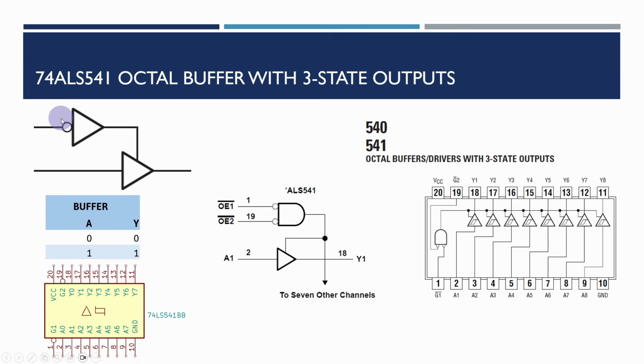And so when the outputs are disabled, generally with the circle here, it means that when this input is low, then the output will be enabled. When it's high, then it's disabled. This means that we can have all the different things that we'd have, like RAM, EPROM, floppy disk controllers, hard disk controllers, and video controllers, all talking to the same data bus, but not actually conflicting with each other.